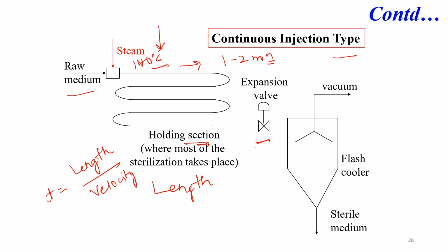And then we are going to have this expansion valve where you can have the flash cooler, and at the end you are getting the sterile media. So, here we are continuously injecting the steam.